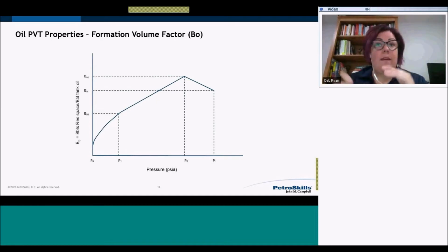So it's still expanding, and it's expanding, and it's expanding. And that's increasing the volume of the oil until we hit the bubble point. And then all of that gas that's expanded in the oil, now as we drop below our bubble point, is allowed to come out of the oil. And it separates now into two phases. So our remaining oil now has a smaller volume again. Depending on how much gas is dissolved in that oil, for volatile fluids, this can be quite a significant volume change. And again, it's something that, as we're looking at rate calculations and surface volumes, we need to understand over time.